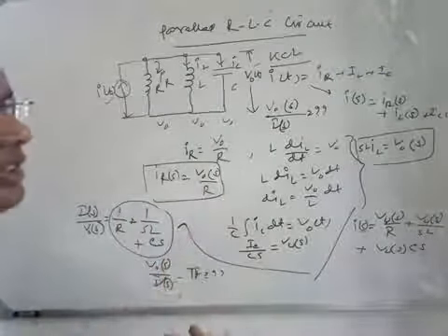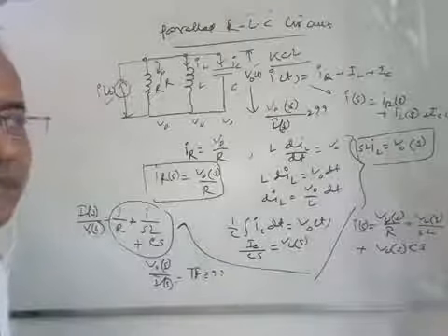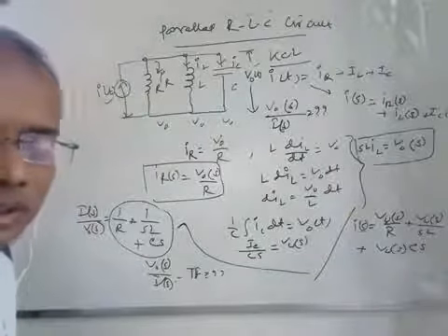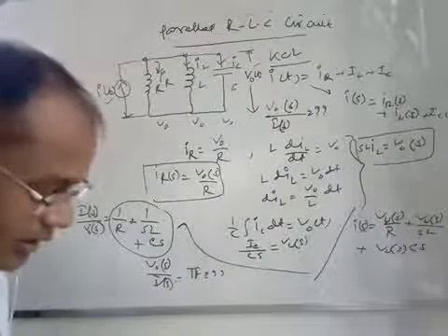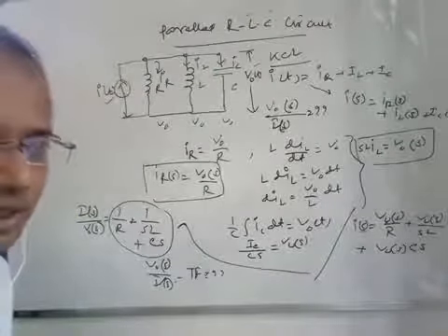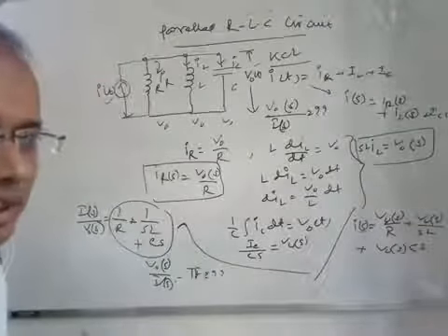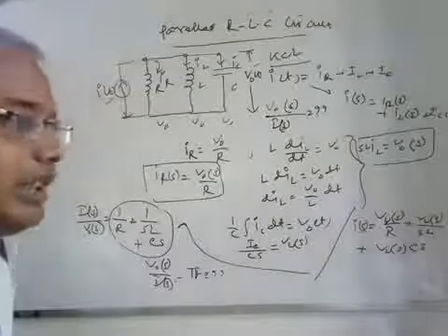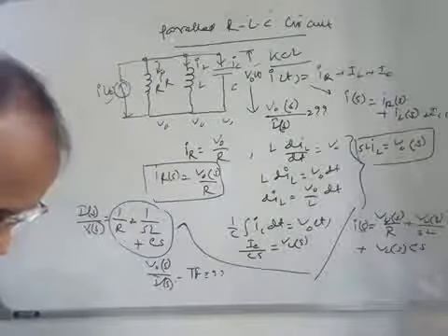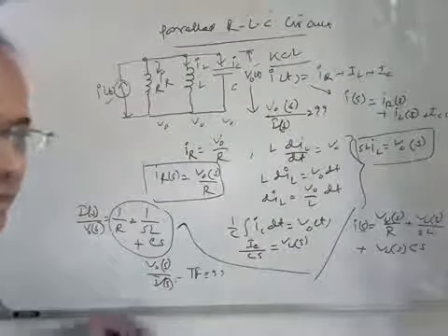In the differentiation part, if you take the Laplace transform of it, we get s into something. And if you take the integration part, the Laplace transform gives 1 by s into something. So that is the mathematical modeling. We have done the series RLC circuit, the series RL circuit, and the series-parallel RLC circuit. That means the electrical network consists of either current or voltage sources, inductor, resistance, capacitance, and they are either series connected or maybe parallelly connected. So whatever the connections, you have to find out the transfer functions, right?